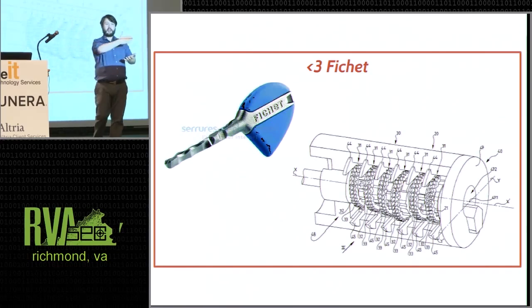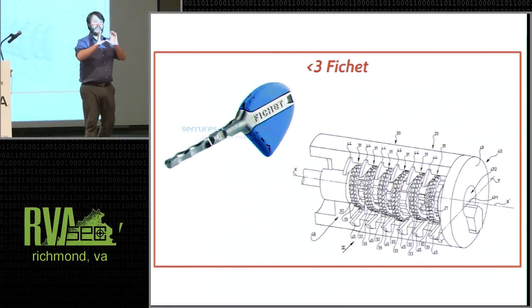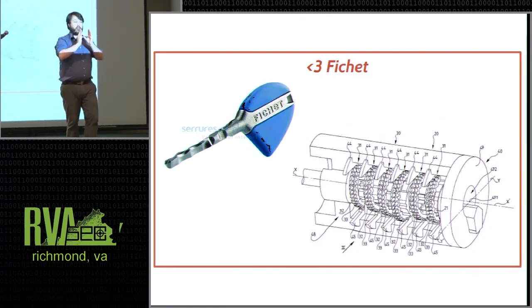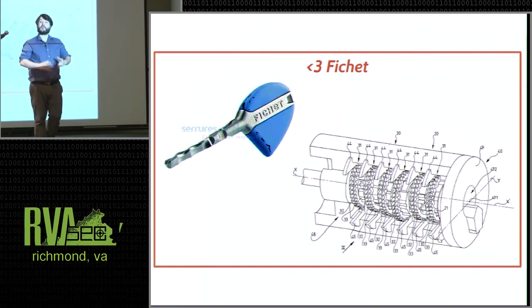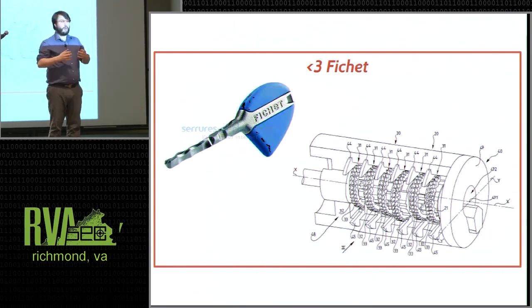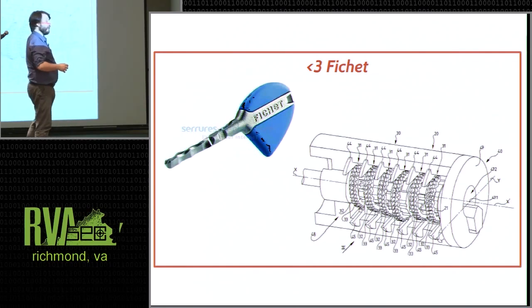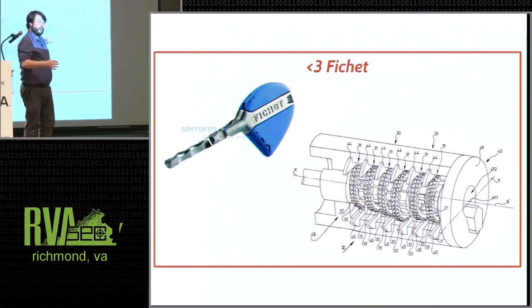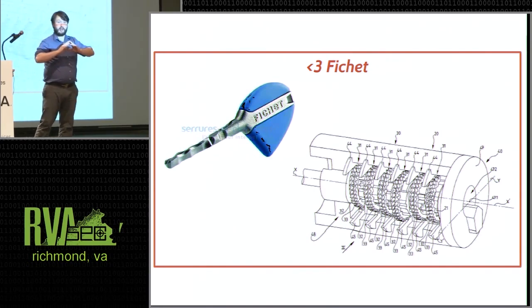As they're dragged along in the channel, that gate is drawn back and forth, and when all of the gates are aligned, a sidebar on either side will be able to drop into place. It's a really, really, really cool lock. However, all of the components inside of it are exactly the same as one another. Every gear is the same as every other gear. Every triangular bit is the same as every triangular bit. Every sidebar wafer has its gate in exactly the same place.